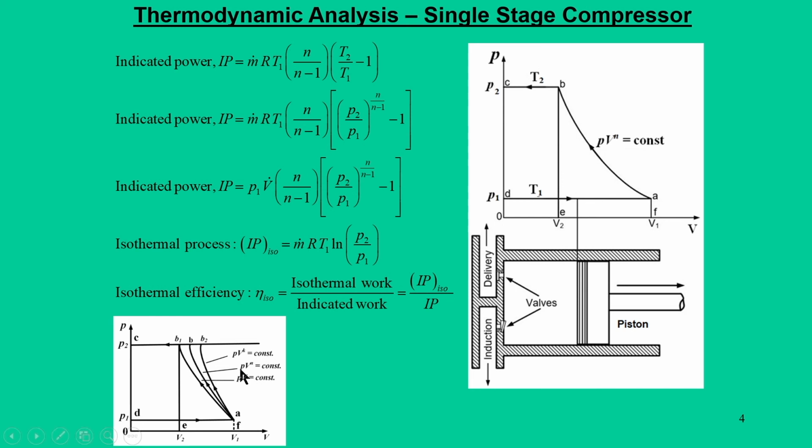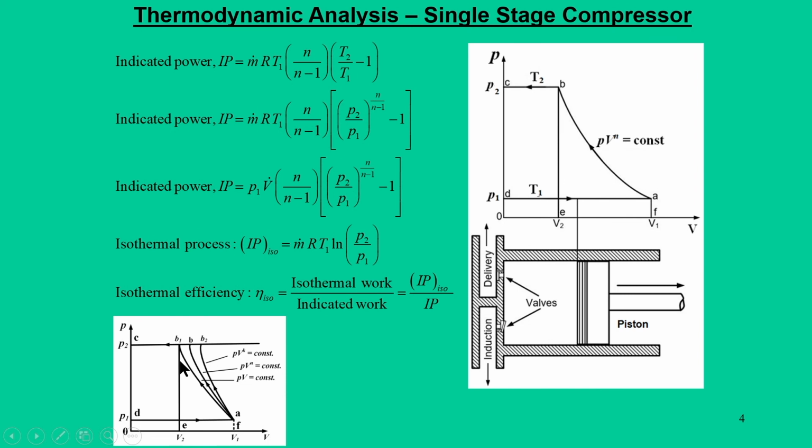So, the isentropic process is not advisable, and the isothermal process, although it goes for minimum work, is not a realistic version, because when you do this compression, the temperature is going to increase, and it is very difficult to maintain a constant temperature isothermal process while undergoing the compression. So, the ideal nature of this compression process is normally dealt with P v to the power n is equal to constant, and typically the n value is kept in the range of 1.2 to 1.3.